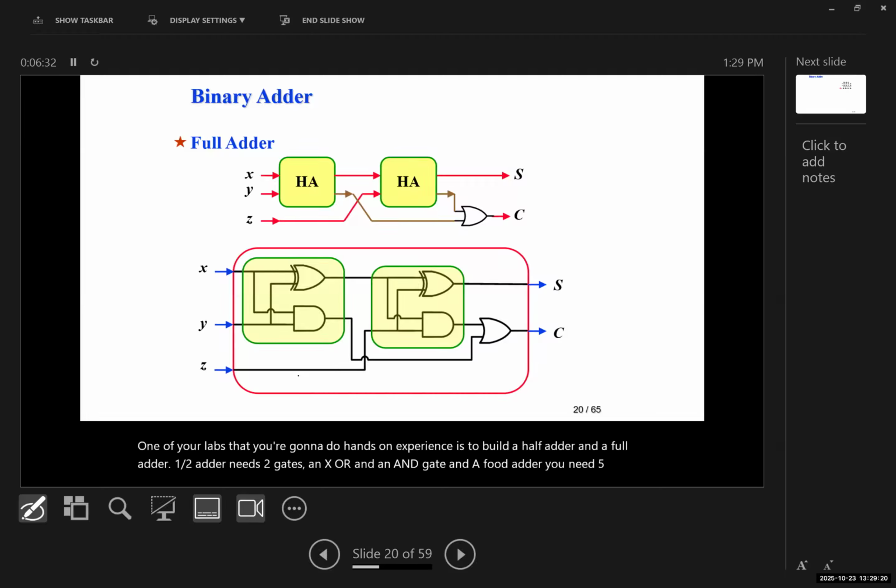So we have a carry propagate addition. We have certain ICs which have these full adders already embedded. You don't have to wire them and connect different full adders together. One example is a binary adder, where you're going to have 8 inputs, 4 bits from one number, 4 bits from another number, and you're going to have 5 outputs. And there's C0, which is the initial carry in. You can connect that to the ground. You would usually always give that a 0.